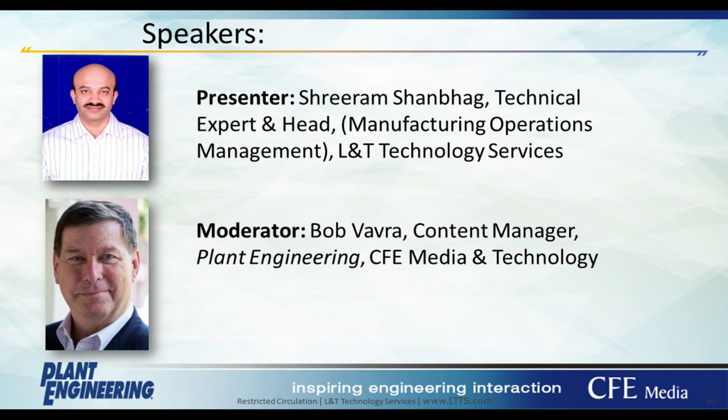Can we do better? Yes, it would be better with vibration monitoring, because even with electrical parameter changes, it may not be easy for us to detect the overall equipment condition. Unless, like in a CNC machine, the quality of electrical power is very, very important. So yes, it makes sense there. However, is it true across all the typical assets? No. I think vibration monitoring is far better. But if we have both, yes, they can be complementary.